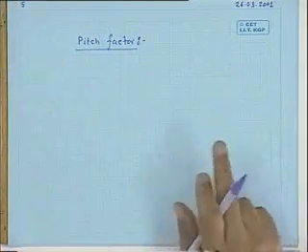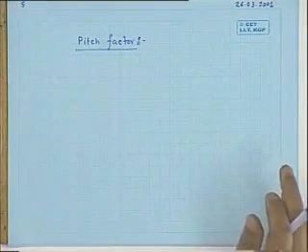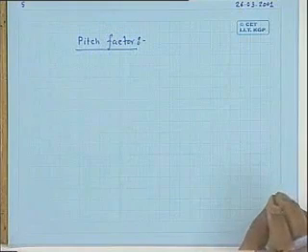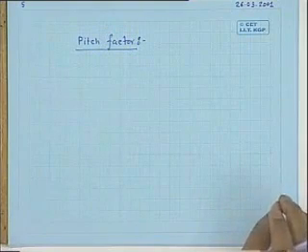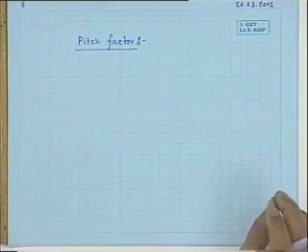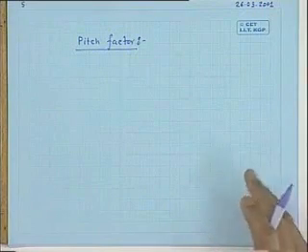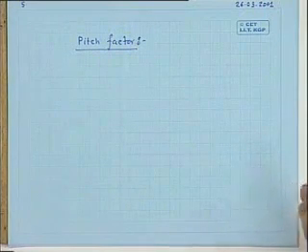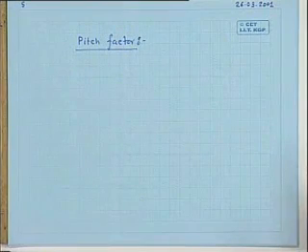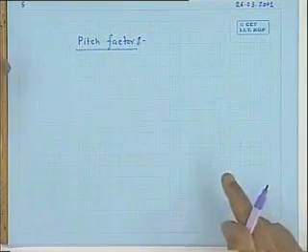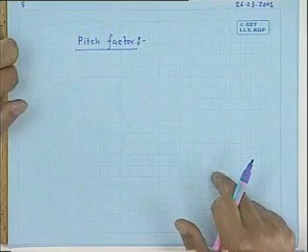Also, I have assumed that when a full pitched coil carries direct current, the MMF distribution of a single coil is rectangular in nature, and I am considering only the fundamental component. There will be induced voltage because of other harmonics also, which we have neglected so far.